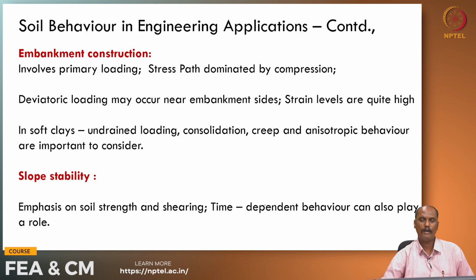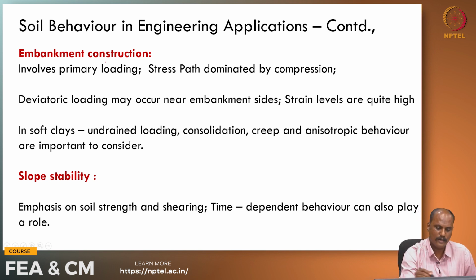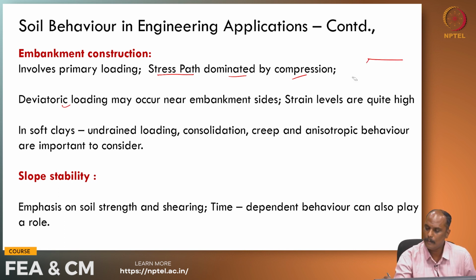When it comes to embankment constructions, we have the primary loading, and the stress path is dominated by compression. Deviatoric loading may occur near the embankment slopes.